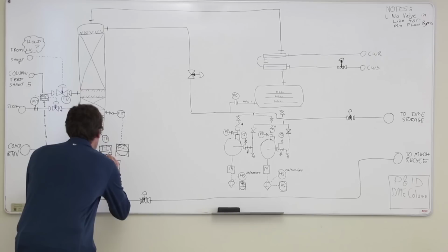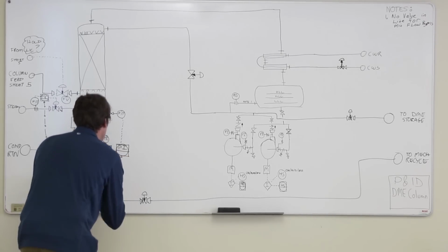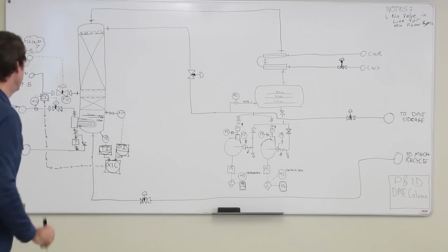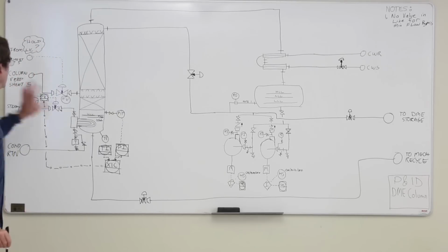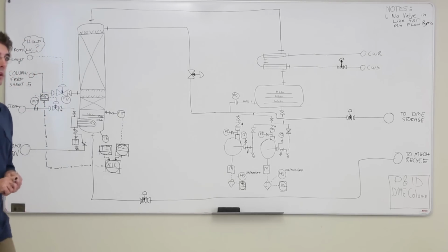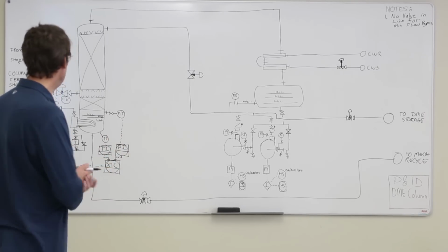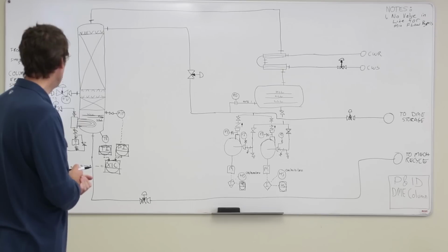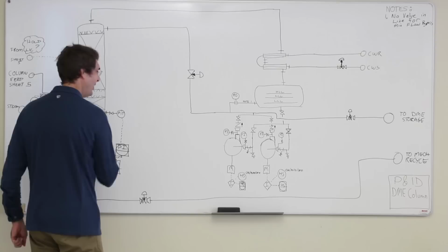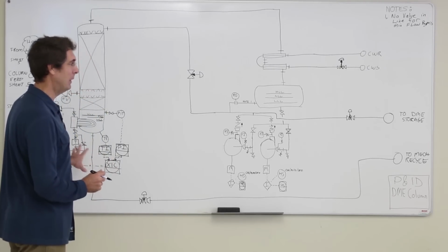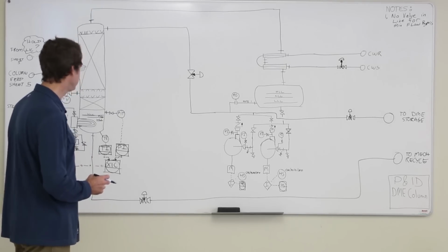We're going to send the software values of pressure and temperature into the composition controller, and then that's going to send a signal to the flow control. Judging from a little bit of experimenting in the simulation, I think that's a pretty reasonable way to do that composition control. We're not really too worried about what the composition is down here. It could be a fairly loose control.